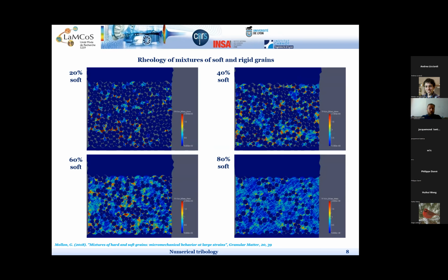And instability will occur if the resistance to shear of the interface, this black curve here, decreases faster than the pulling load on the interface. In this case, you have some unbalanced force here, which means some acceleration and some dynamic slip.